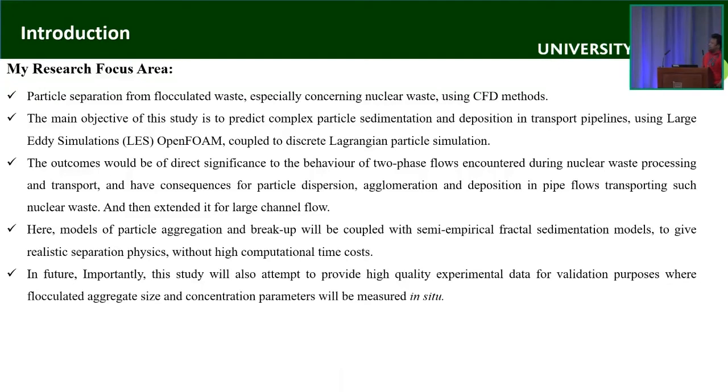Here, models of particle aggregation and breakup will be coupled with semi-empirical fractal sedimentation models to give realistic separation physics without high computational costs. In future, this study will also attempt to provide high-quality experimental data for validation purposes, where flocculated aggregate size and concentration parameters will be measured in situ.